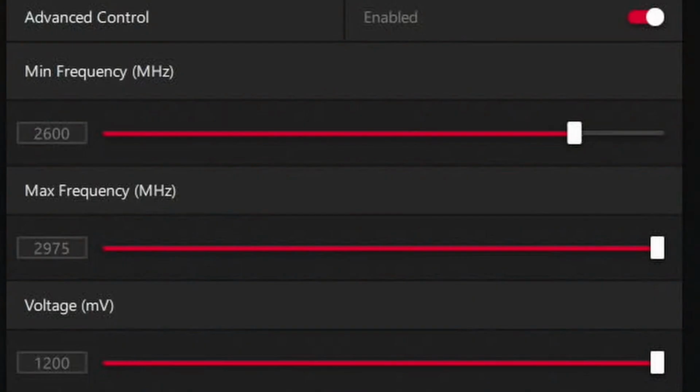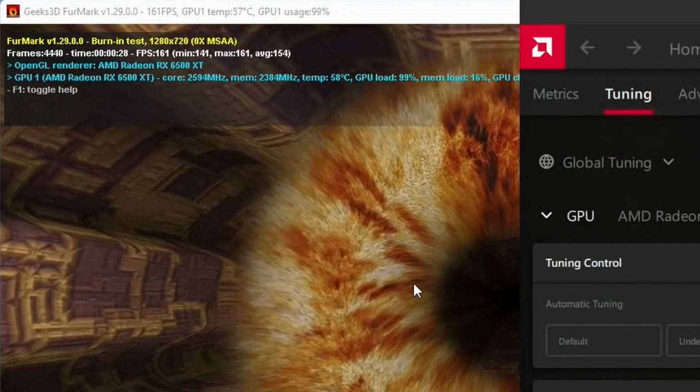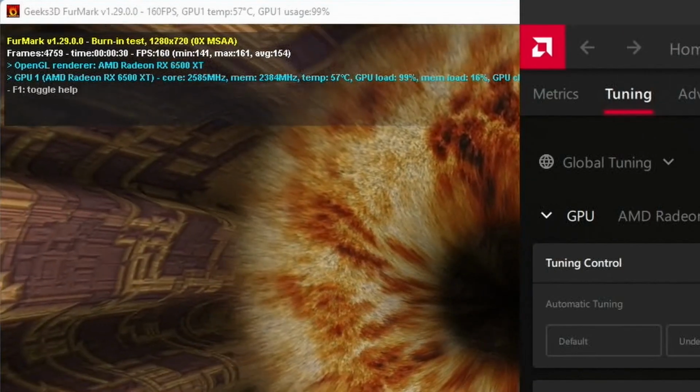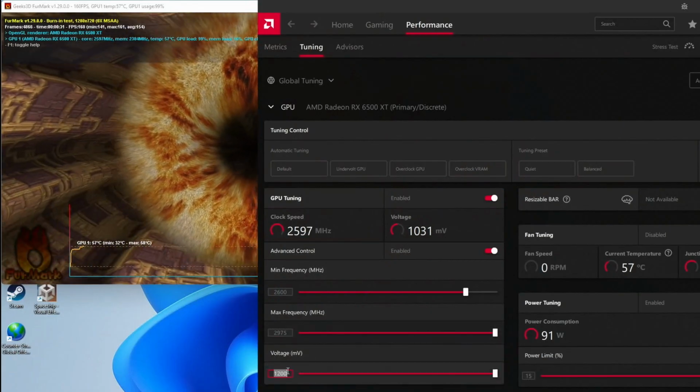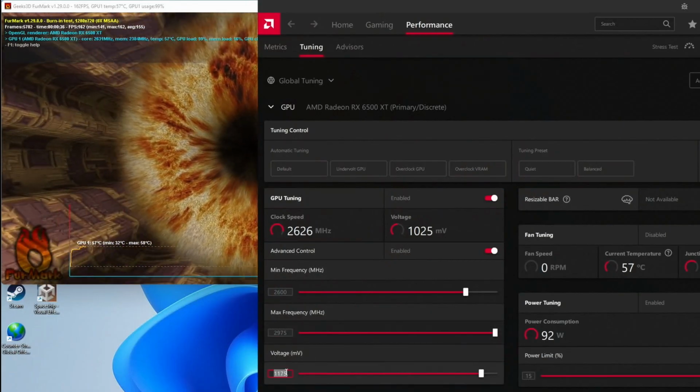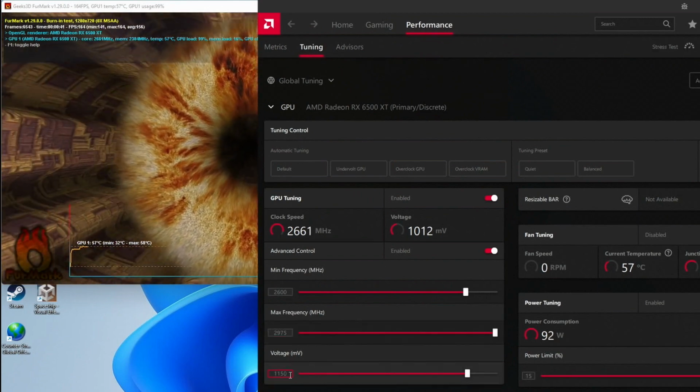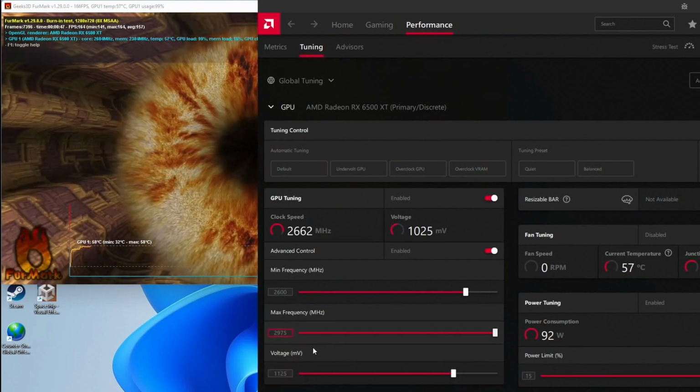My approach to GPU frequency tuning is as follows. First, open the Adrenaline software and set the minimum GPU frequency to the highest value that doesn't cause performance throttling. Then, keep the FurMark GPU stress test running and monitor the current FPS. Reduce the GPU voltage setting to negatively offset the voltage frequency curve until you see graphical errors on your screen.